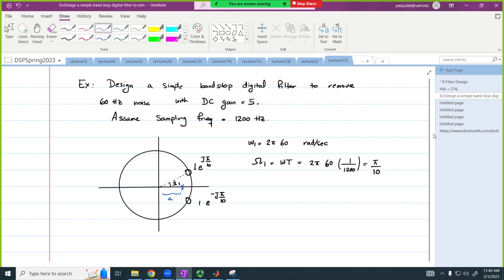With the band stop, you would need some type of value, I would assume, around the 60 hertz, right? Like, rather than it just being a notch, you want to stop some epsilon around 60 hertz, right? What this filter is going to do is remove the 60 hertz 100%, and around it is going to be attenuated. Make sense? Now, depending on what I have at the input, maybe I just have an interfering signal and nothing around it.